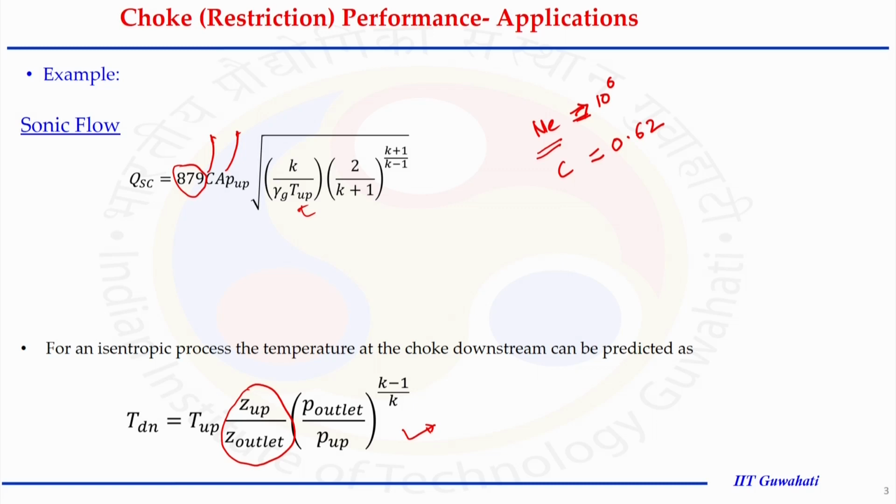If the downstream temperature is very low, yes, we need to apply heat. For this case, we get a downstream temperature of 5 degrees Fahrenheit, which is lesser than 32 degrees F. Yes, we need to apply heat across the restriction. Similarly, the Q we are going to get, as a numerical value I can provide, is 12,743 MSCF per day. So I think the picture is clear on how to choose a particular model equation to represent the flow through the restrictions.